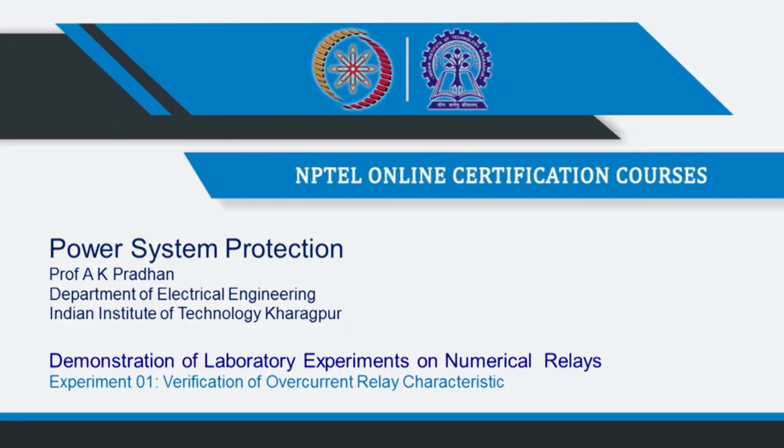So, we have first the demonstration on the overcurrent relay. We will verify the overcurrent relay characteristic, particularly as we have learned in the theory. Here we will be demonstrating one characteristic, the inverse definite minimum time IDMT characteristic, widely used in different power system applications.